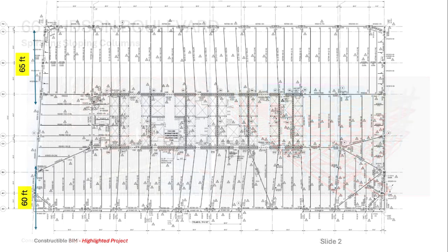So I'm going to show you 5 floors quickly. I'd like you to focus on what I call the horizontal truss work. Depending upon where those spiraling terraces are, that's where you have the sloping columns. Sloping columns create forces that want to push or pull on the building locally.